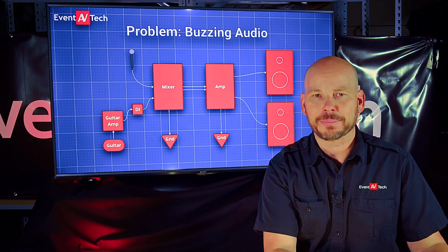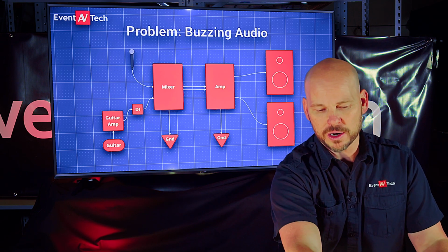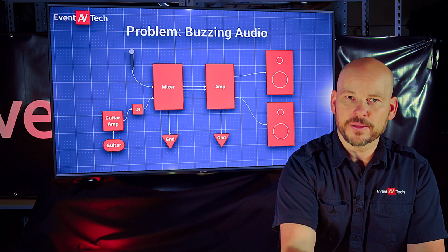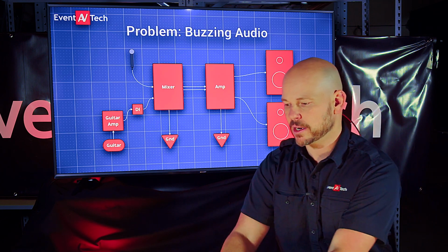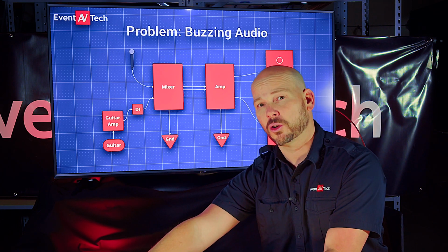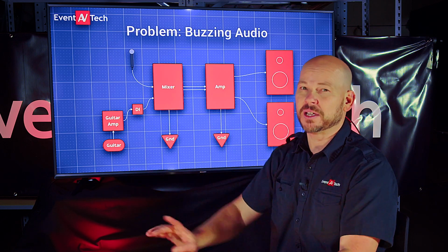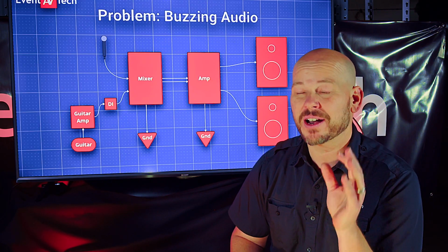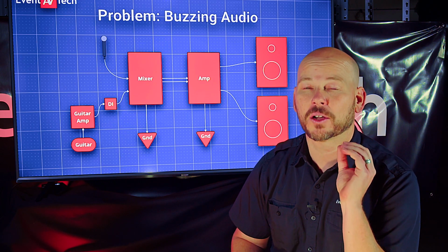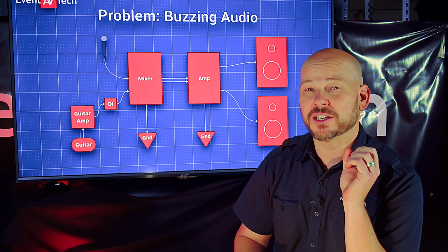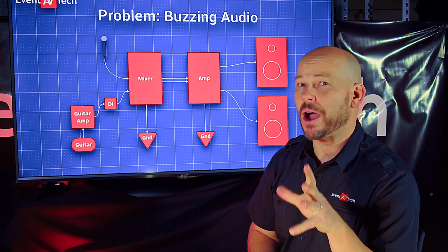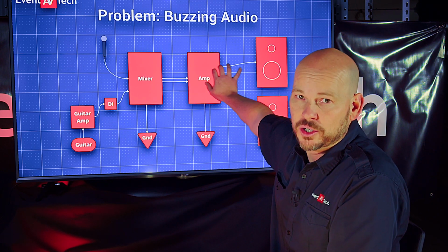Like if you took your laptop and you don't connect it to power, you're running off your laptop's battery, and you put in your 1/8 inch jack out to an auxiliary and you send a signal down the lines that used to be connected to your mixer. The reason is when you're running off a battery, you're not connected to the ground. So by doing that, I'm isolating the ground and I'm trying to identify, do I have a power issue or do I have a signal flow issue?